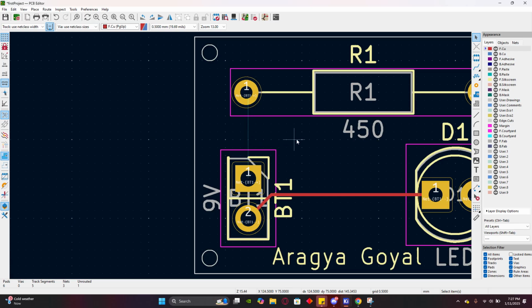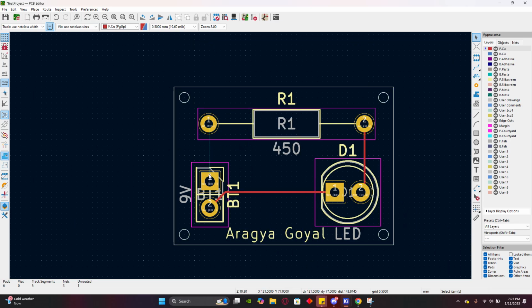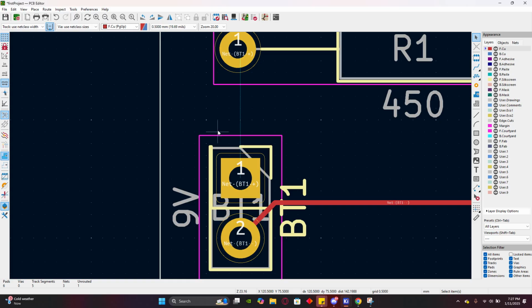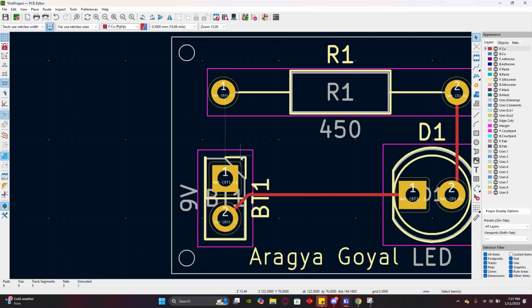When you lay out your components, you want to minimize these lines overlapping each other, because if I wanted to do something between this one and, I don't know, two, and then one and one also, and they happen to overlap, I would either have to put it on the back copper layer to avoid them. But since we're only working on the front copper layer right now, you want to avoid any of those interfering with each other. That becomes more of a problem when you're working with more components.